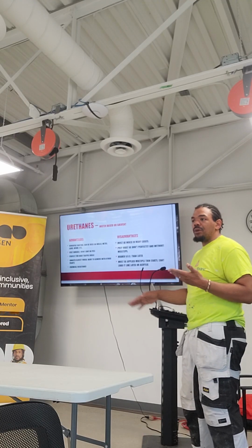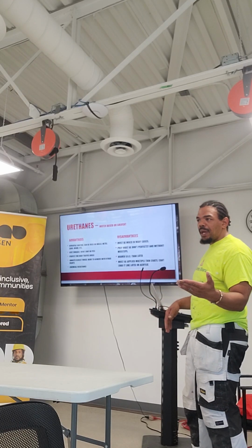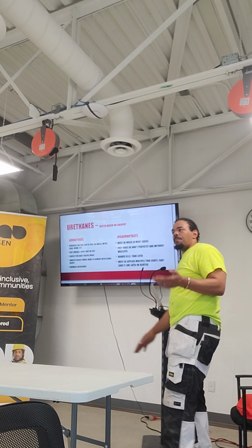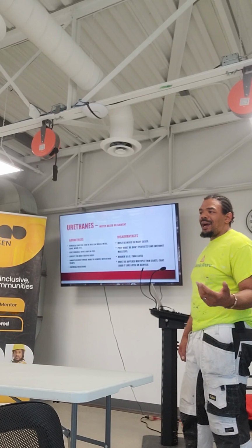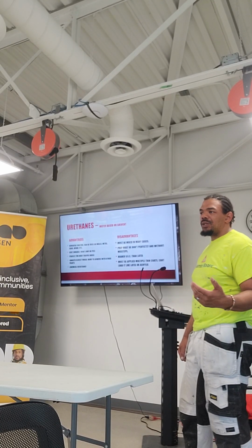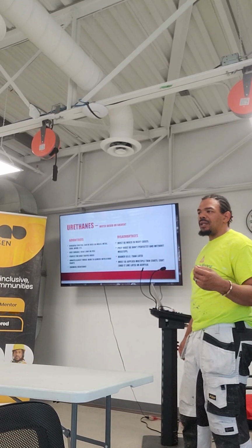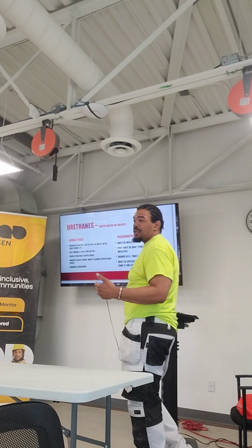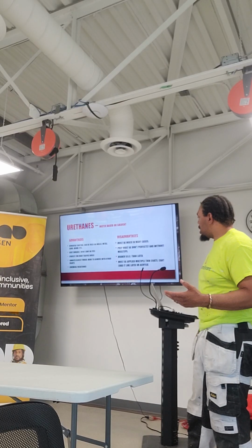You have to wash it with the chemical to clean all of the dirt and all of the contaminants, even after you paint it. Any dust that settles on the urethane, you have to remove. Urethanes, in a lot of cases, should be applied in a shop, or in very sterile conditions where there's not a lot of dust or dirt or wind or sun. It's very, very temperature and condition sensitive. So they have to be done correctly. Sometimes you have to be creative with the prep, and creative with how you prevent issues from happening.